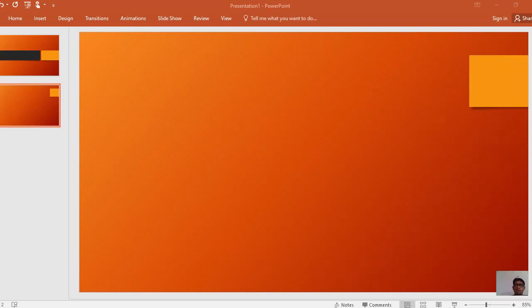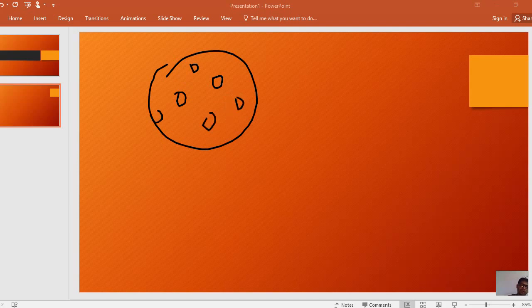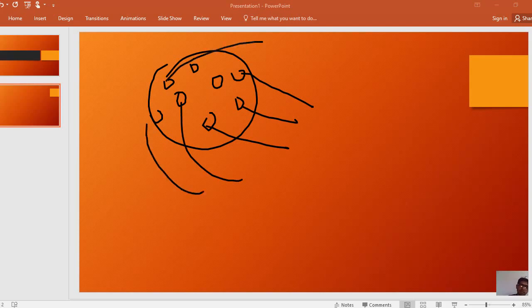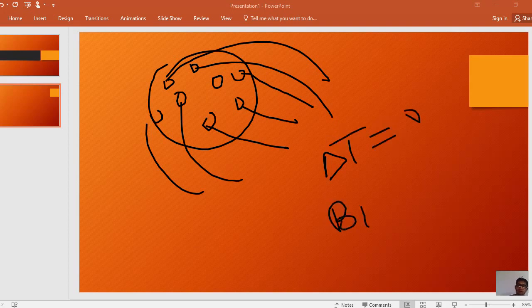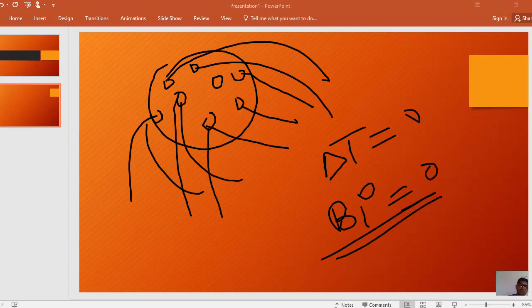In transient heat conduction the temperature changes with the passage of time, and in the lump system the temperature was considered to be constant at every point. In the lump system the temperature at every point in the object was considered to be the same, and the temperature difference was 0. The Biot number for the lump system was 0, but in reality there is a small temperature difference. At different points the temperature difference can be slightly different.